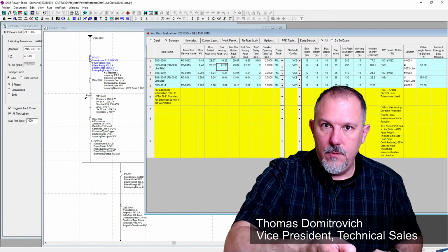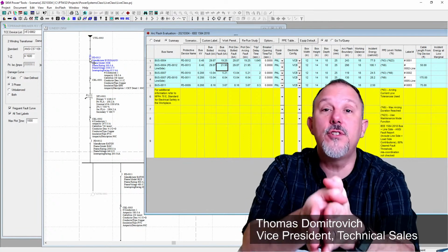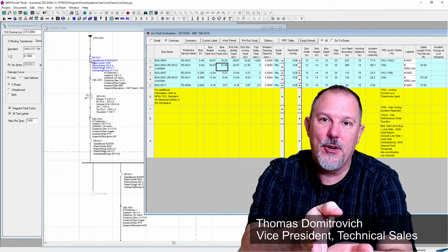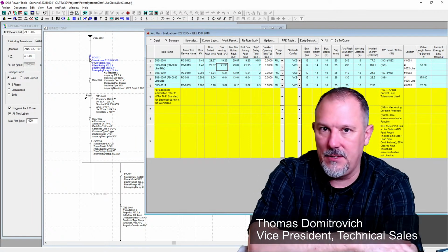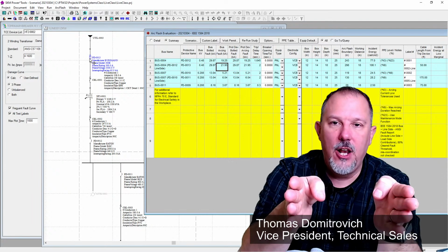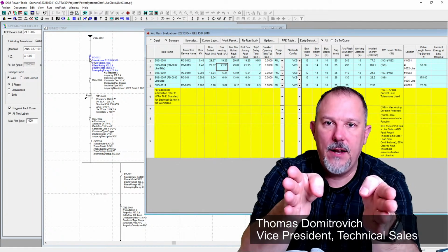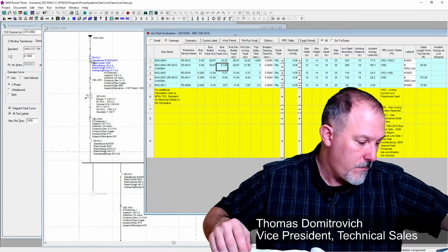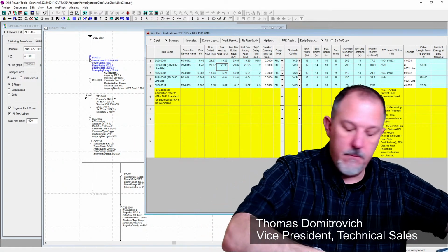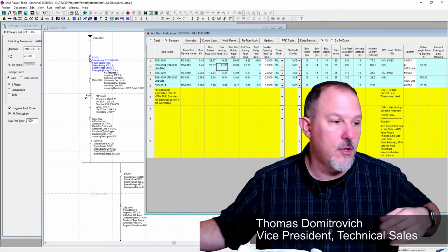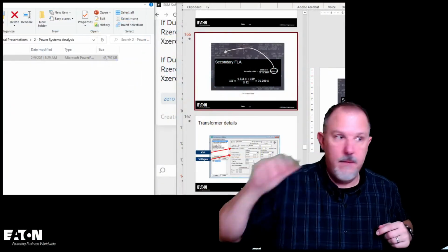What we used to do in the 2002 version, remember, we calculated a value of arcing current and then they said take 80%. And we would calculate a lower value, and you would compare the clearing time of both of those overcurrent protective devices.